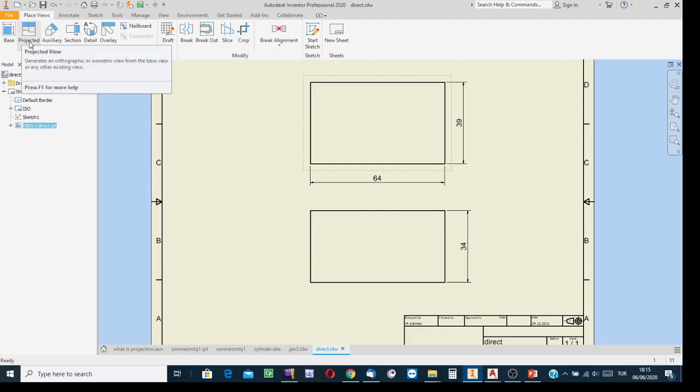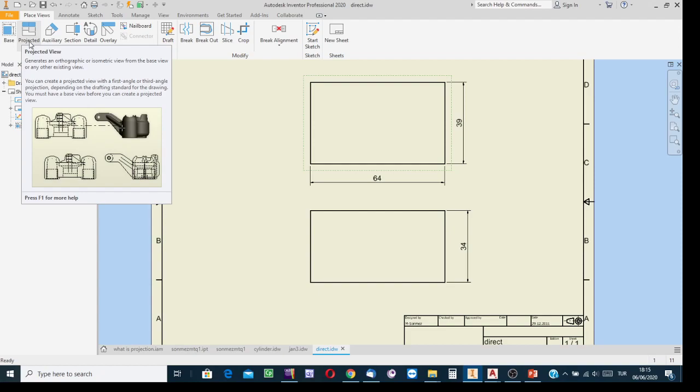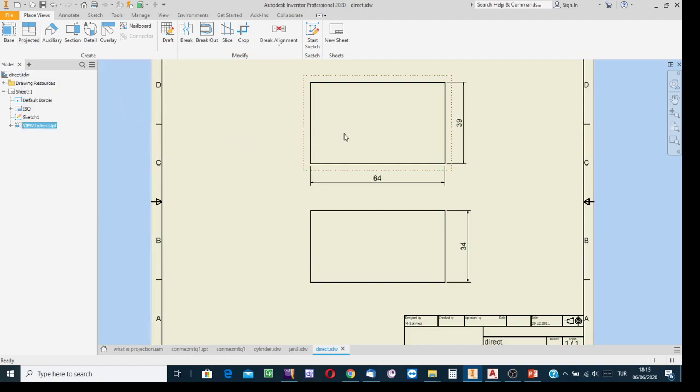Actually, the projected button is clicked by the software while we are creating 1, 2, 3, 4, maximum 5 principal views, in the background on behalf of us. So the views are created as consistent views with respect to each other. You know this. After seeing that here, this is the front view, this is the top side view, see what the front view is in shape.